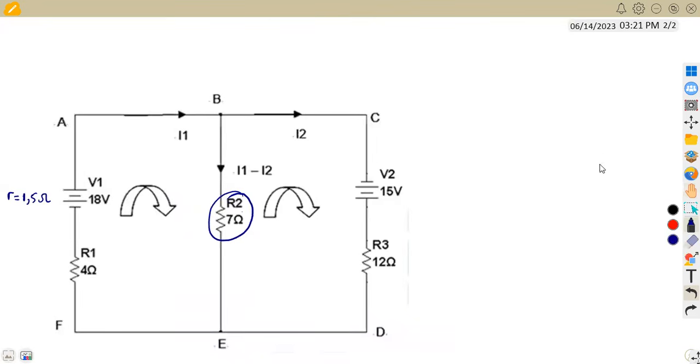All right, so remember what we've got on our Thevenin's theorem. I explained these stages before. The first stage is to find the VThev, which is found by removing the load resistor. So we remove the load resistor, which is the 7 ohm resistor. By removing it, we represent it across AB, and this is where we are going to calculate VThev.